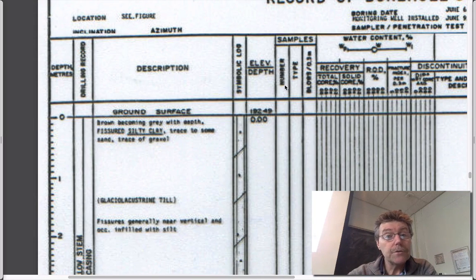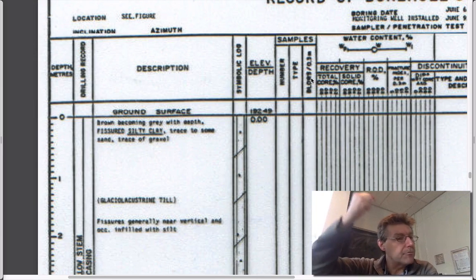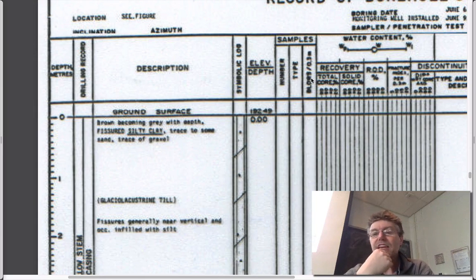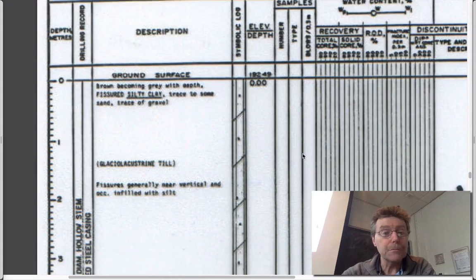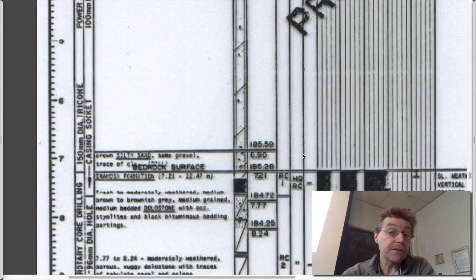Elevations, some documentation of what samples were taken, how many, what type, and blows per 0.3 meters, metric Canada versus blows per foot. You saw the monkey hammer banging this thing into the ground. We said that this Torvane is something that classifies the soils in terms of the strength, stiff or soft clays. Classifying sands, which you can't sample that way, is done by driving this split spoon physically into the ground. How many bangs with this hammer do you take to go 1 foot? Rudimentary, but there's 50 years worth of data that can tell you lots of interesting things about the soil from that. Not permeability, but lots of things about the engineering properties, strength.